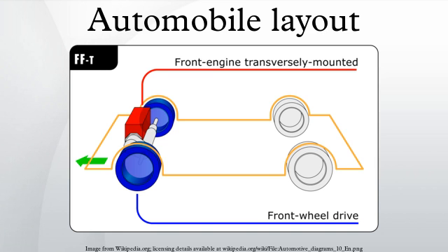Some rear-engine cars can suffer from reduced steering ability under heavy acceleration, since the engine is outside the wheelbase and at the opposite end of the car from the wheels doing the steering. A rear-wheel drive car's center of gravity is shifted rearward when heavily loaded with passengers or cargo, which may cause unpredictable handling behavior. On FR cars, the long drive shaft adds to drivetrain elasticity.